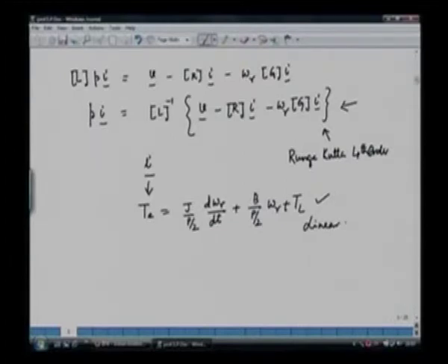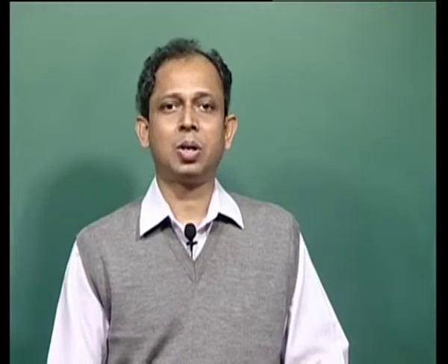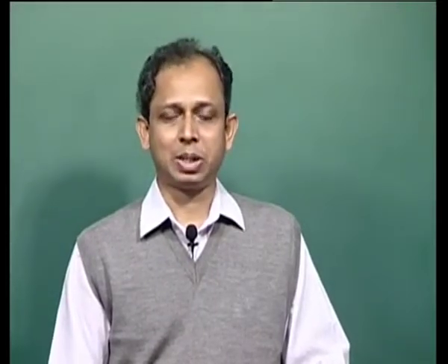And after we obtain the torque, we can simulate this equation by linear integration technique, and first order is sufficient. We can just have first order linear integration, which will be much accurate to give us the value of speed. So we can find out the speed from this equation, and we know the torque and the speed. So once we know the torque and the speed, we can plot the torque speed characteristic of an induction machine.